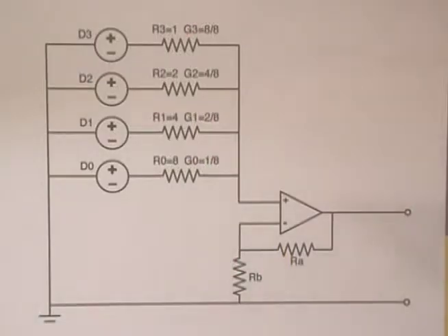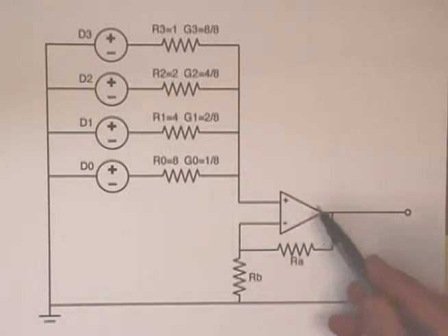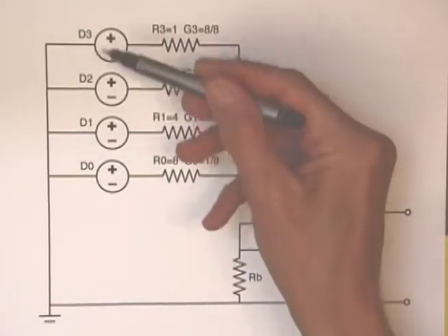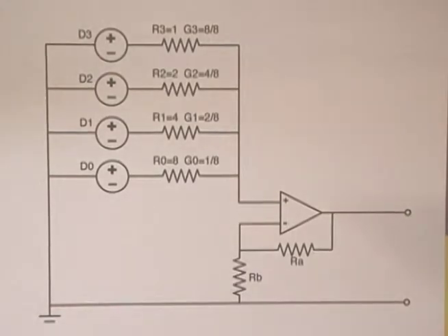After finishing a project, it's a good idea to review what you might do differently next time. There are 3 areas of improvement I'd like to call attention to. The first is in the output stage. It's inconvenient to have to compute and set up scaling for the output amplifier. Commercially available D/A's take a reference voltage, which is the voltage you want to see for full-scale input. Then the D/A outputs a value somewhere between ground and the reference voltage, proportional to the binary input.